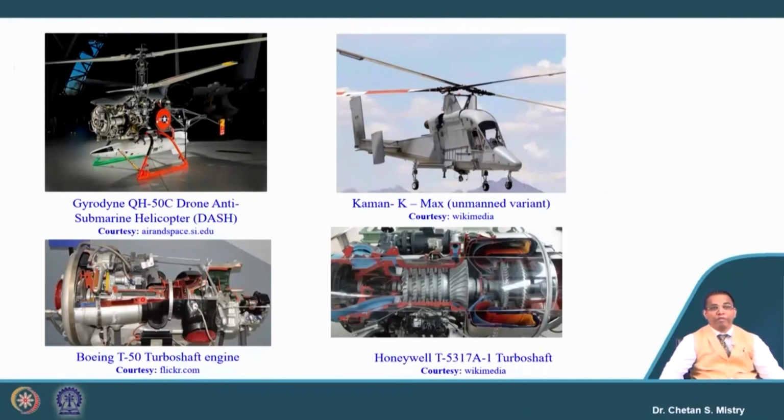If you recall, we have discussed a similar kind of engine for the turboprop engine. So, a turboprop engine also can be used as a turboshaft engine, yes, but you need to do certain modification, or maybe no modification. In a turboprop engine, the thrust we discussed is generated by the propeller as well as by the nozzle. Here in this case, we are not bothered about the thrust.